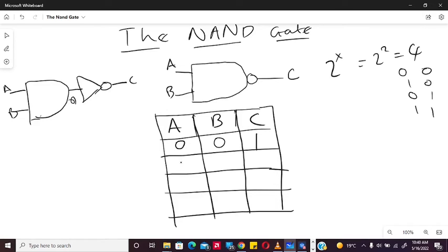So we have an input of 1 there on A, and an input of 0 on B. What do you think will happen? So 1 there, 0 here. So we have 1 0 there. What do you think the output will be here? The output here, as for the AND gate, these values are not the same. They're not all ones. So here it will be a 0 again. When we feed this 0 into the NOT gate, it will be another 1. Let's go on to the other input set.